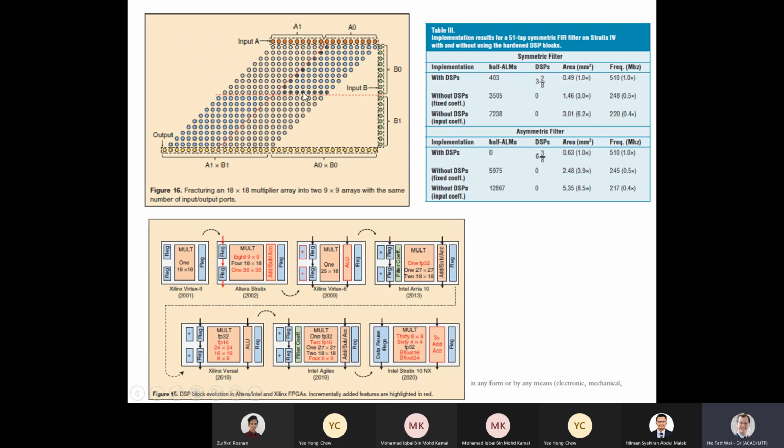Okay, and instead of doing this with the programmable logic and logic lookup tables, you can see the progression from 2001 FPGAs to 2020 FPGAs. In 2001, they give you dedicated multiplier circuits, 18 by 18 bit multipliers, with 2 input registers and 1 output register. Later on, they give you an option where you have four 18 by 18 multipliers, eight 9 by 9, and one 36 by 36, and you can combine them in any which way. And then they also allow you to have an additional add and subtract strap here.